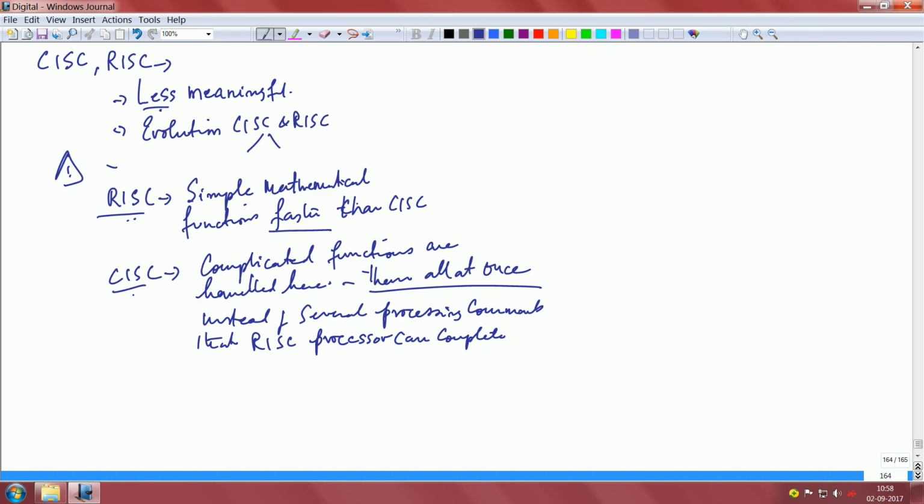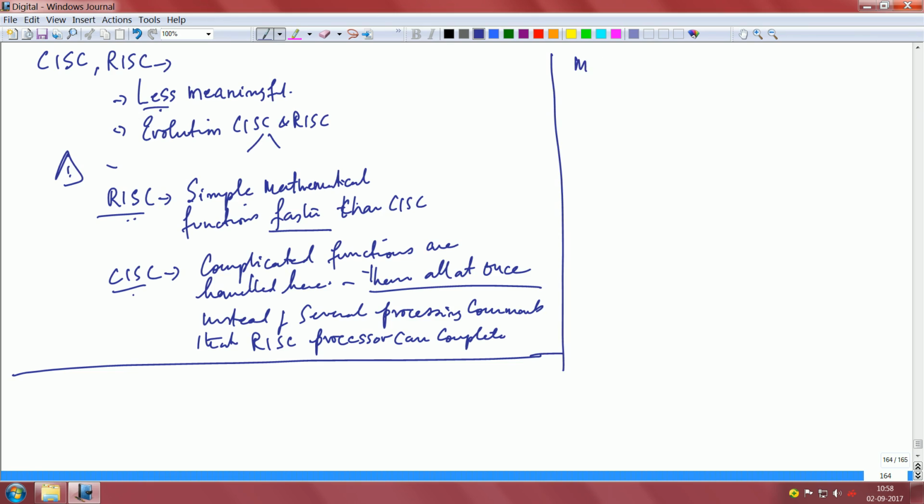Now, this is about the direct comparison of RISC and CISC, okay. Then there are other things. What about MCU speed? Big question. Everybody talks about speed, and vendors talk about how many megahertz it can run. Well, speed has directly got to do with energy consumption, right. Consumption is indeed an issue, and that is to do with MCU speed. That is why vendors will give you a number, so many microamps per megahertz.